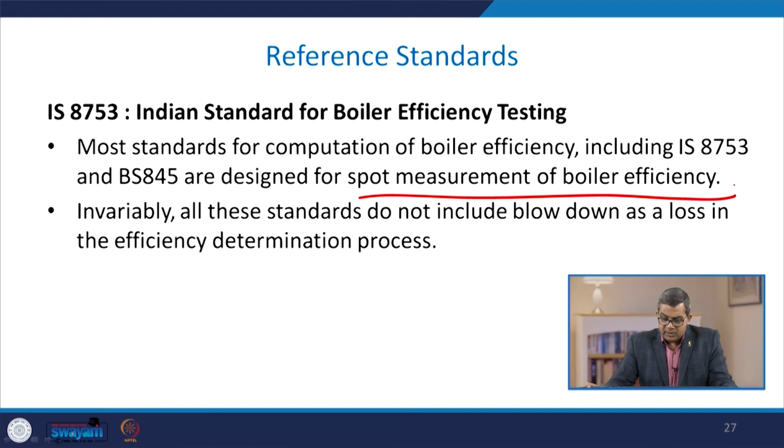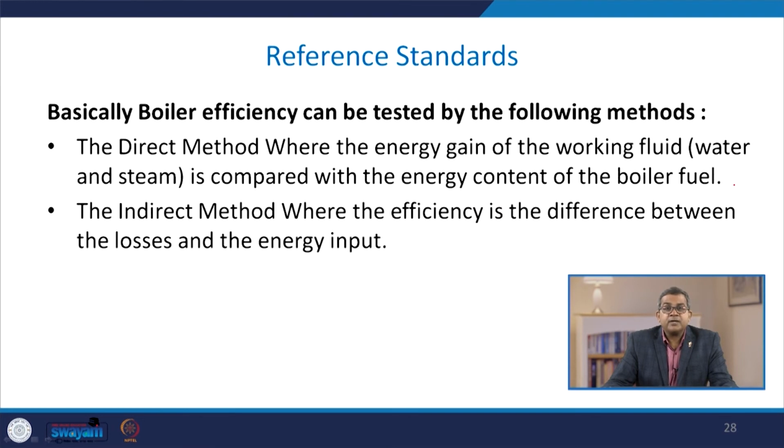Now, I am telling you this because when we go for the blowdown, it also carries heat value. When it is discharged from the boiler, it usually has a temperature equivalent to the boiler, as well as a significant quantity of water. So, if we are not including this blowdown, then obviously there is a flaw in the standard.